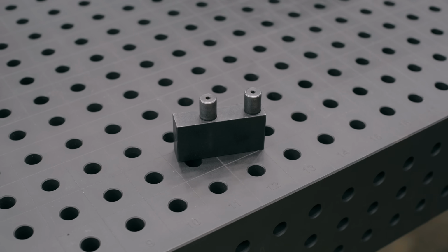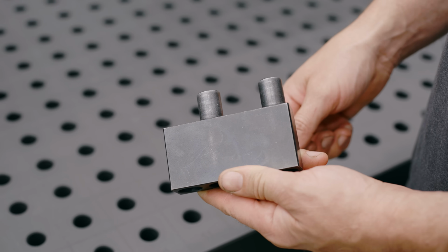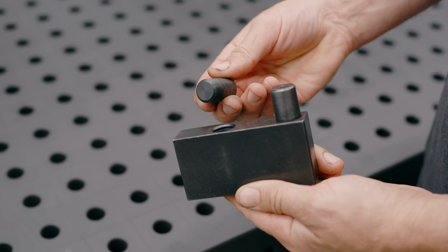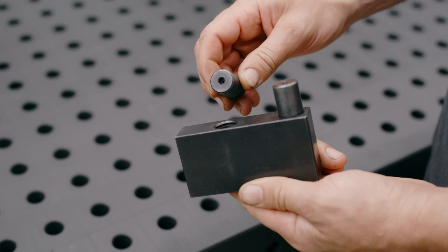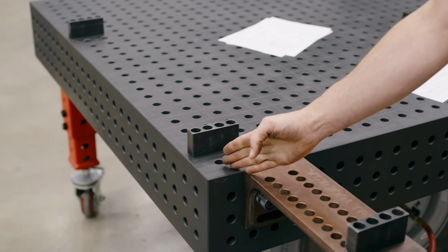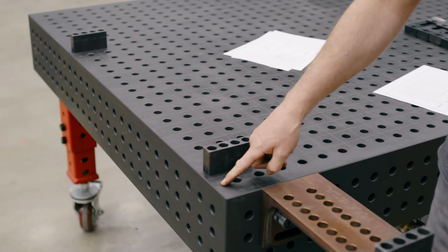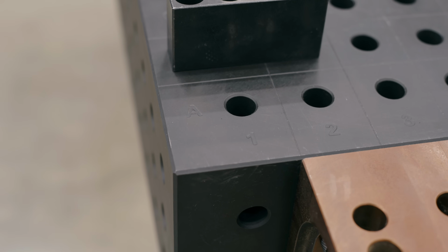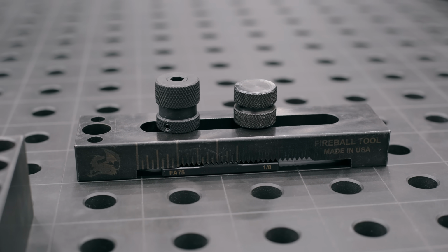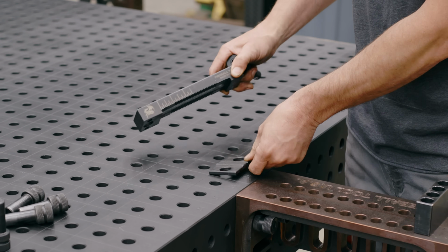Okay, so the next thing is we're going to set our fence blocks up. It's a 1x4 block. Those are all the holes, and it has fixed pins in the bottom. You can take the pins out, we can bolt them into place, or just use the pin like a Lego. And they just drop right in the holes right here, just like that. So if you look at the table, we have a grid in it, 1 through 50 along the front and A through Z along the edge. And they've been etched in the table so they can't ever wear out. That's the whole ID number. The next step was we're looking at tooth blocks. This is the tooth block I was talking about in CAD. You can see the teeth on the bottom and the teeth in the washer.